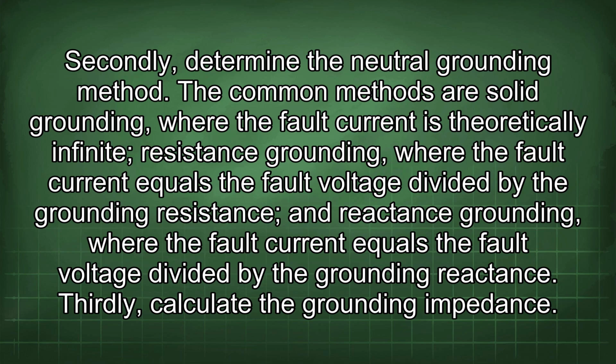The common methods are solid grounding, where the fault current is theoretically infinite; resistance grounding, where the fault current equals the fault voltage divided by the grounding resistance; and reactance grounding, where the fault current equals the fault voltage divided by the grounding reactance. Thirdly, calculate the grounding impedance.